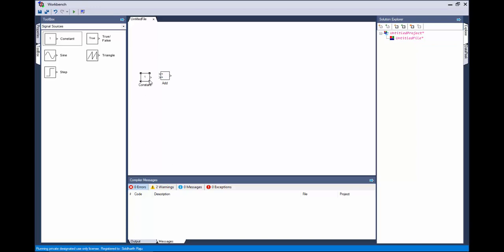In this example, a simple sine PWM of a 3-phase 2-level inverter is shown. A 60 Hz 3-phase reference sine wave centered around 0.5 is compared with a sawtooth carrier of 1 kHz. The output is the gate on-off pulses for the inverter.